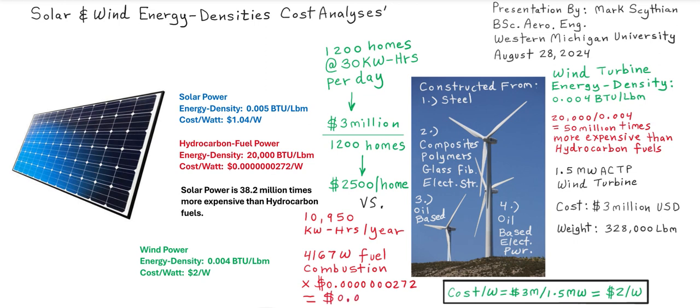And that includes natural gas. It's an equivalent derivative. If you scale all the energy density and fuel density together, you get about the same 20,000 BTU. For example, a pound of natural gas is 24,800 BTUs. It looks like it has more energy density, but then its fuel density is much lower, 0.041 pounds per cubic foot. So it comes back down to all about 20,000 across all petroleum, or I will say hydrocarbon derivative fuels.